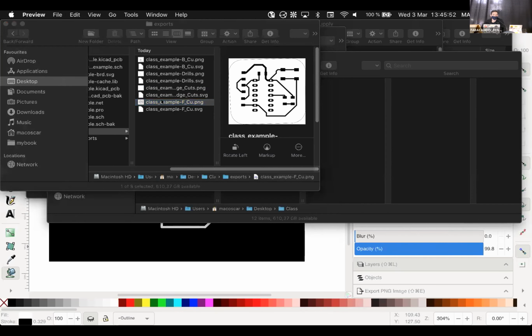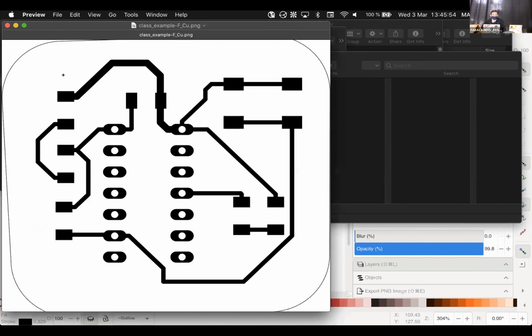Let me open it like this, it will show. So here we have this outline in black. When you put it in mods, it will also make the cuts for the outline with the small end mill. This is not bad for the PCB, but it will take more time. So you need to go faster. You can remove this line, and the holes are the same.